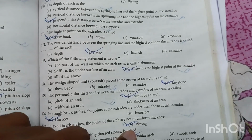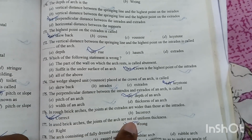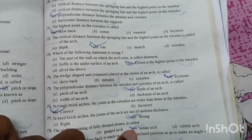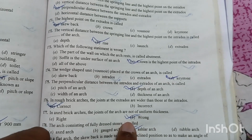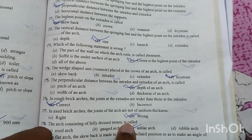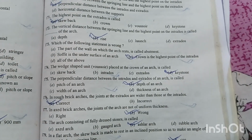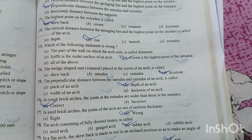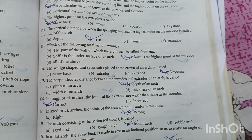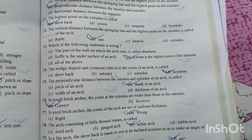Question number 175. The perpendicular distance between the intrados and extrados of an arch is called depth of an arch. Option B is the right answer. Question number 176. In rough brick arches, the joints at the extrados are wider than those at the intrados. Option A is the right answer. Correct answer. Question number 177. In axed brick arches, the joints of the arch are not of uniform thickness. No. Option B is the right answer.